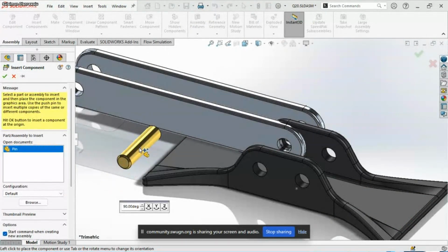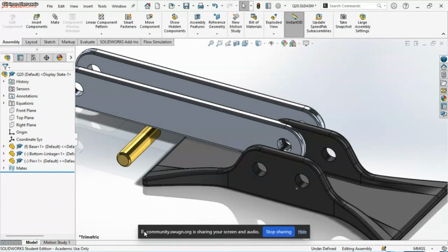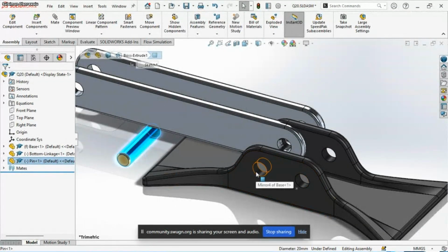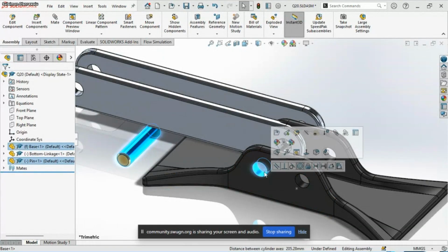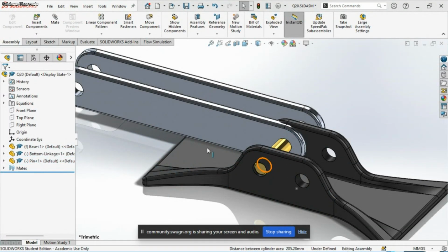You just click it there and select the two and make it work concentric. I hope it's concentric. I use the first time. So it has to be concentric, not coincident. Concentric. So as we've done that, the next